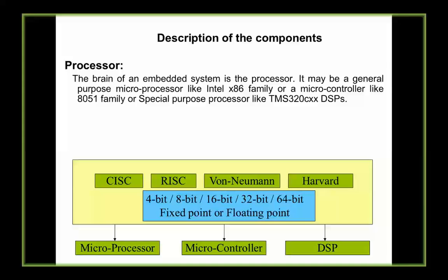It cannot be eliminated. So you shouldn't think that microprocessor means interfacing is required and microcontroller means it is free from interfacing. Absolutely wrong. It reduces the amount of interfacing and flexibility because it comes with this much ROM, this much RAM, this many IO pins, everything built in. So you cannot extend them very easily. Again, if you have to, you incur some kind of extension, and you're back to what you are doing in a microprocessor. So you have to choose carefully between them.